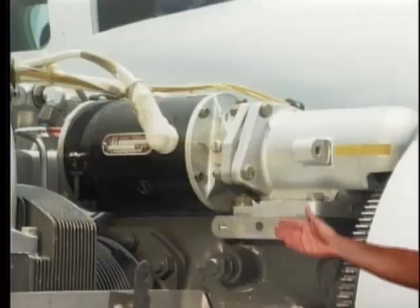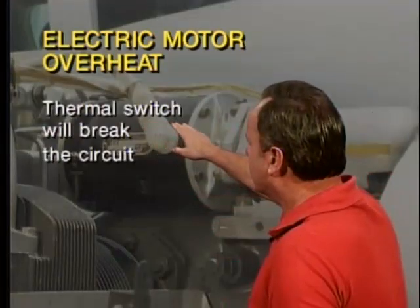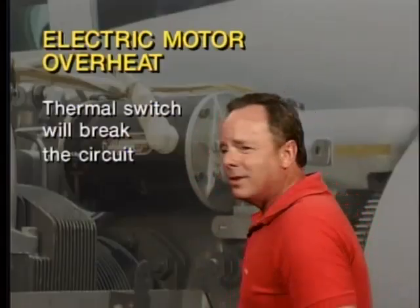Now here is an electric motor that could occasionally overheat. Now, what is the desirable thing when an electric motor overheats? Well, the desirable thing is this. You have a thermal switch in the electric motor that breaks the circuit and prevents a fire. That's the desirable thing, and that's what they tell you will happen on the test, that when an electric motor malfunctions and overheats, it can incorporate a thermal switch that will break the circuit.